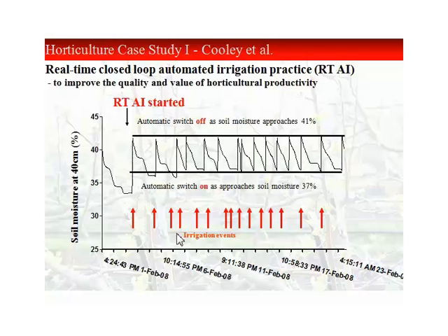The red line indicates the automated irrigation events. This is when the actuator, which was a solenoid, was turned on and off based on the soil moisture percent. The solenoid was turned on when the soil moisture reached 37%, allowed to irrigate for a period which changed in time depending on the conditions, and was switched off at 41%.